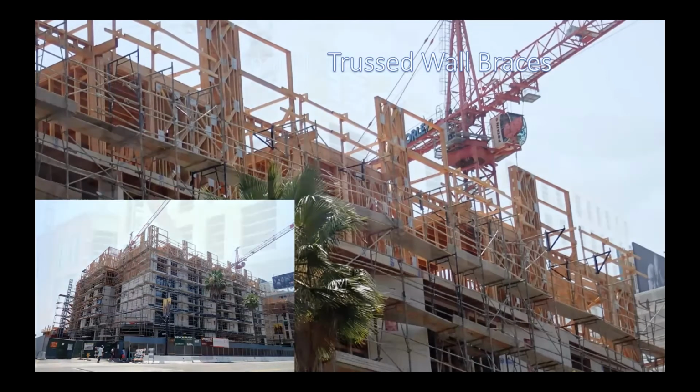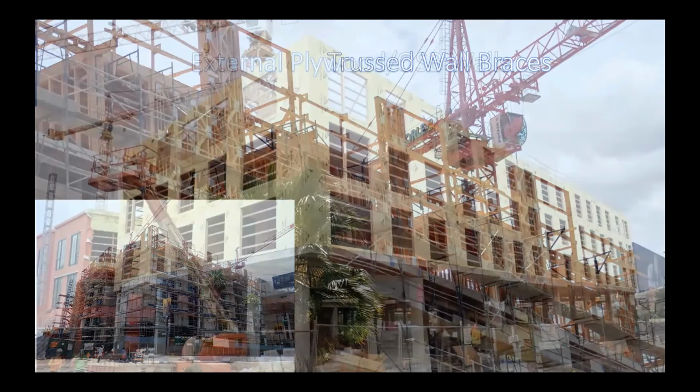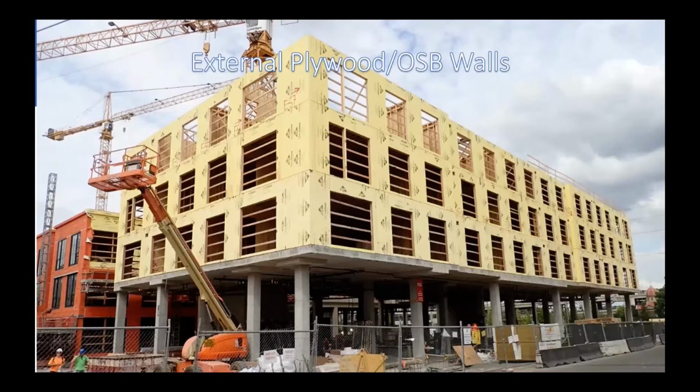But by and far, the most common way of accomplishing bracing over there is to encase the whole building with plywood or OSB. And this, in conjunction with a whole lot of tie rods and other systems, creates a very nice little eggshell for the structure, a nice little shoebox, if you like. And that's the most common way of doing it over there. And as you can see, like Dean's building in King Street, there's quite commonly a concrete podium below that allows for different functions of facilities to be incorporated downstairs, anything from car parking to commercial activities.